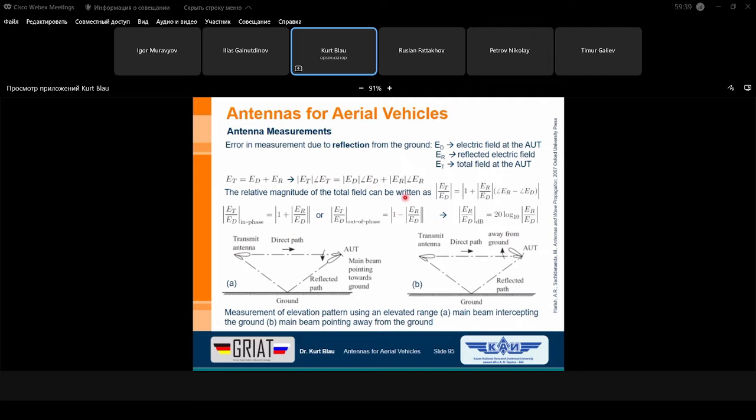And if we only look at the error itself, then we can assume it as this quotient. In dB, it is nothing else than the quotient in linear scale, by 20 times the decade logarithm of this value. Then this is our measurement error.